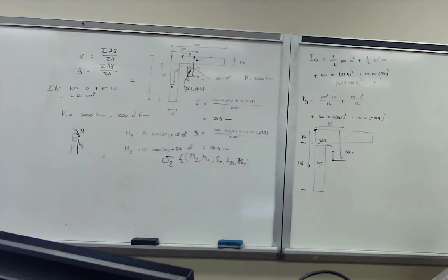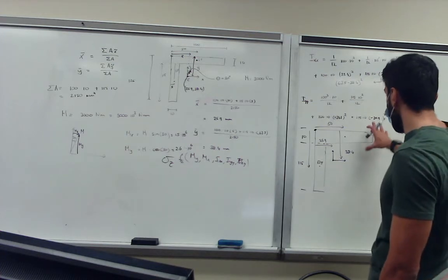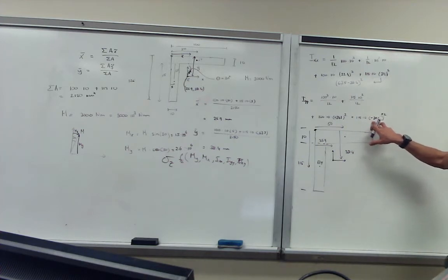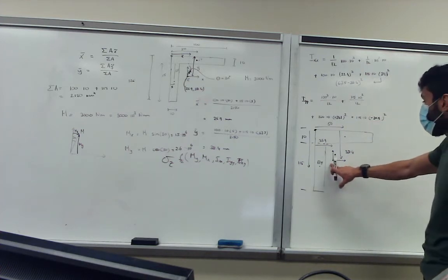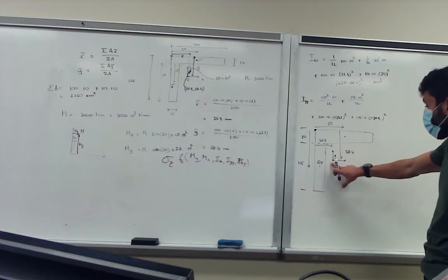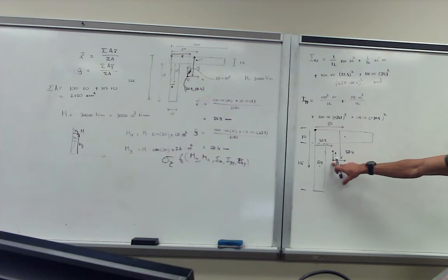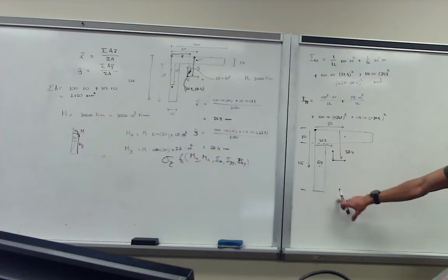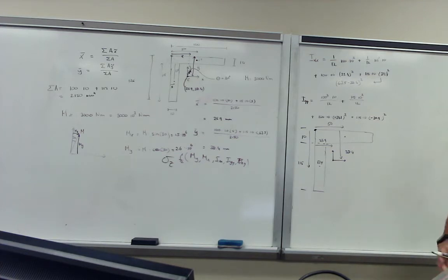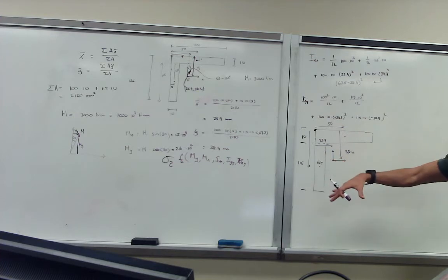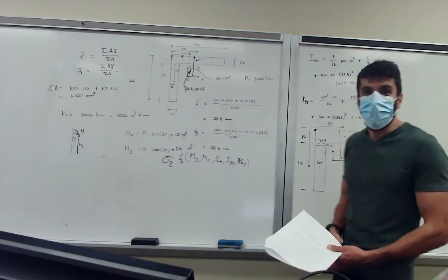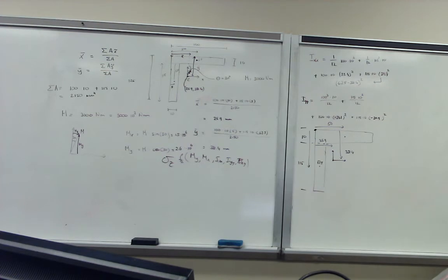Why is that negative? In this case, how I would put this as a negative. It doesn't really matter for this case, but the next one we see is how it compares with respect to this axis. This was your coordinate system, positive x, y, it lies beneath it, so therefore the negative sign. It's going to be squared, it doesn't matter. It doesn't matter for this one, but now we see the x, y, it does matter. Why are the values different then for IXX and IXY? Or sorry, IYY. Like, why is one 33.4 and the other's 24.1?